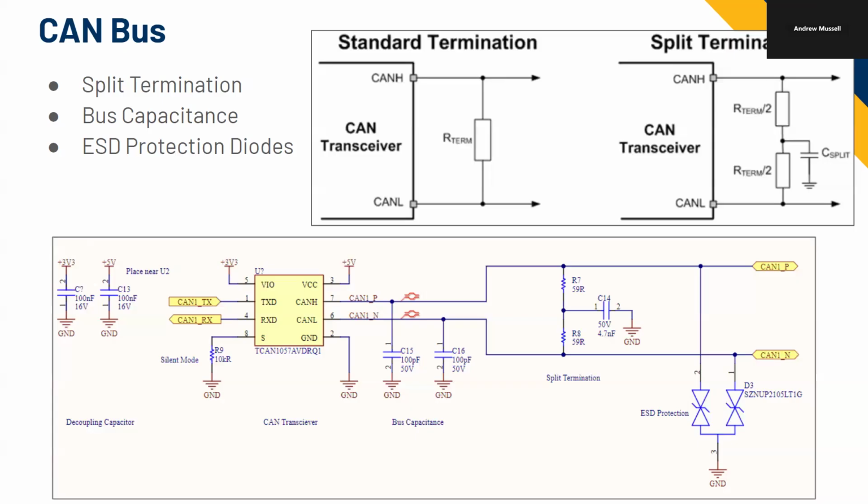Diodes won't conduct at all, and then they'll hit their forward voltage, and then they'll sort of go like this. It's not perfectly straight because there is some real component to it, some linear resistance. And then normal diodes just go like this. No matter what the negative voltage is, they won't conduct. In reality, eventually even normal diodes can't block infinite voltage, so eventually they'll break. None of these markers are really good. Eventually they'll break, right? Can you see that? So normal diodes will break.